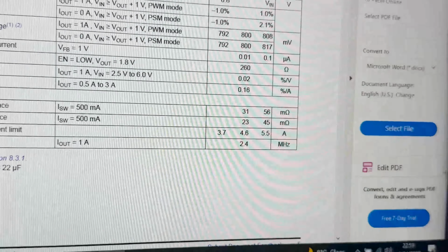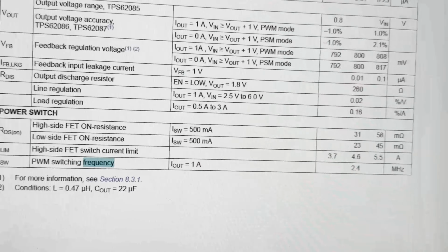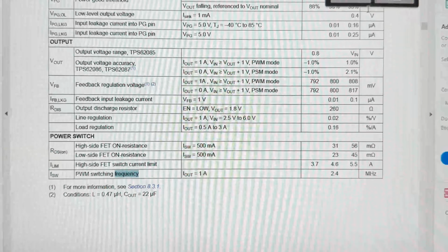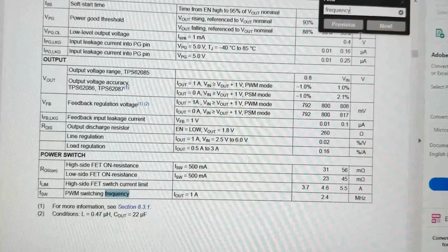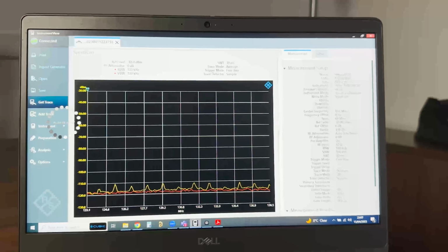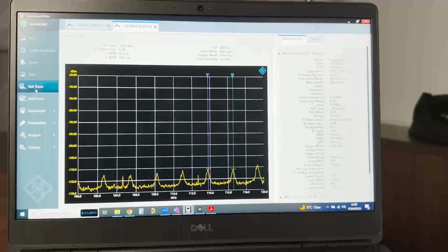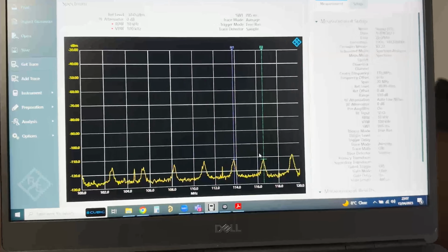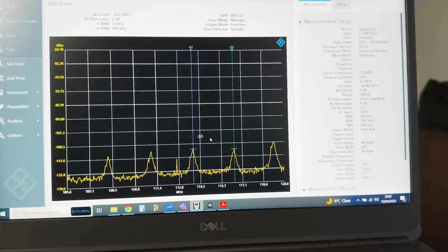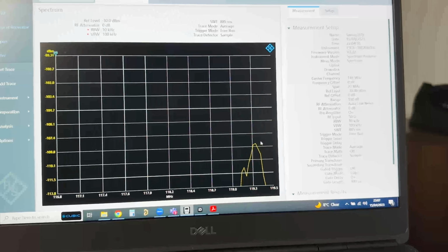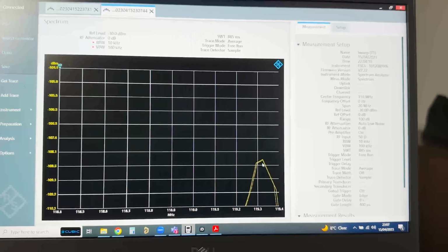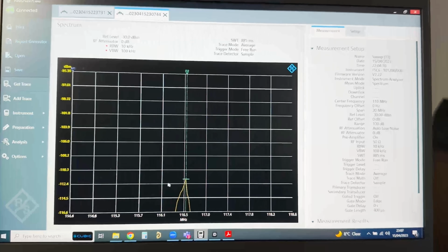And there is some uncertainty when it comes to measurement with spectrum analyzers. I can now get this new trace I was just looking at, and this is now allowing me to capture it on a big screen, so I can see quite precisely where the center frequency of that spike is.